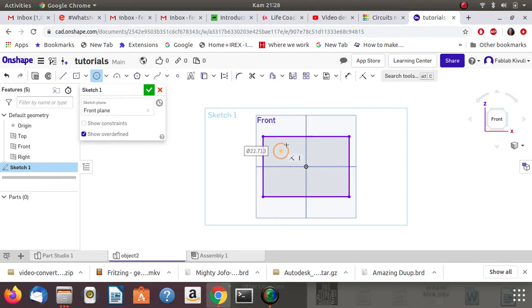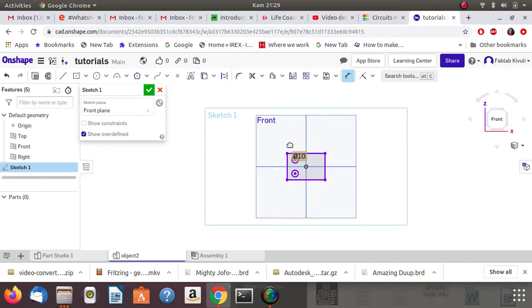So if I want the hole to be the same size and the same distance from this plane, I just go to mirror along this plane, and then I'll say I want the other hole to just mirror itself there. And then I'll go to dimensions and decide that hole is 22. Wow, well, let's just say 10 millimeters,